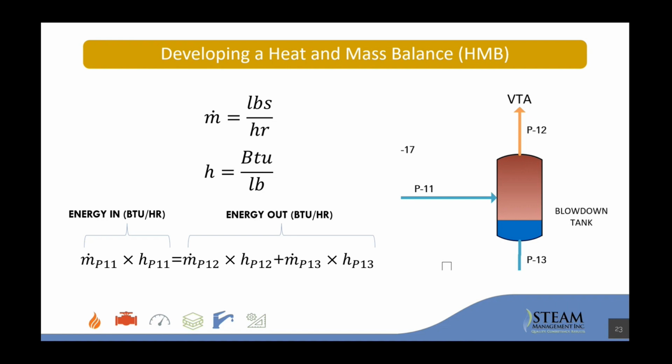But yeah, if you do go into reducing system pressures, you've got to keep an eye on the velocity in your steam piping, because as your pressure goes down, your velocity goes up for the same mass flow, and you can get your steam screaming through those pipes too fast if you're not careful. Anyway, good question. Yeah, so back to this.